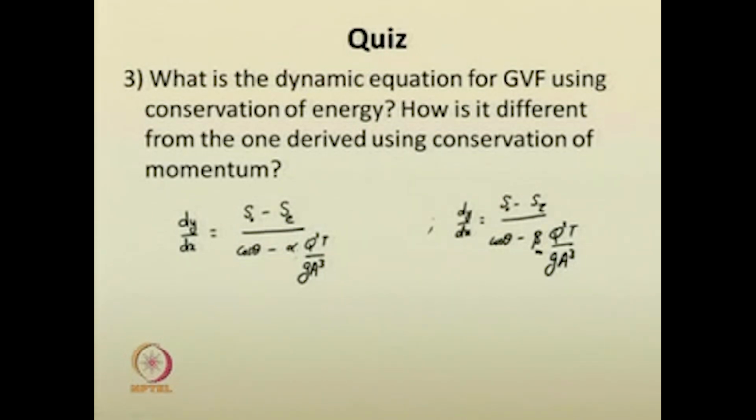For the correction factors, you had used the kinetic energy correction factor in the energy equation, whereas you use the momentum correction factor in the momentum equation. So, that is alpha and beta m, those differences are there. So, therefore, they are not the same. In principle, they are different, because kinetic energy correction factor and momentum correction factor can differ for any channel section. Similarly, the energy slope as well as the shear slope can also differ.